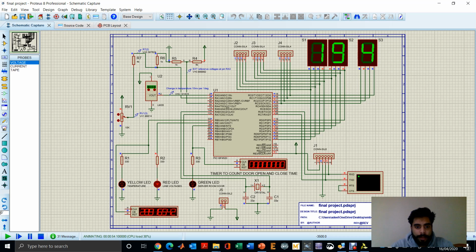So let's see what happens if we increase the temperature again, to 23. It will take some time, take the average of the recent 5 readings, and then it will show the change in the output, which will potentially turn on this LED. That timer only represents the first 25 seconds, which I use to show that the code is working according to the requirement.